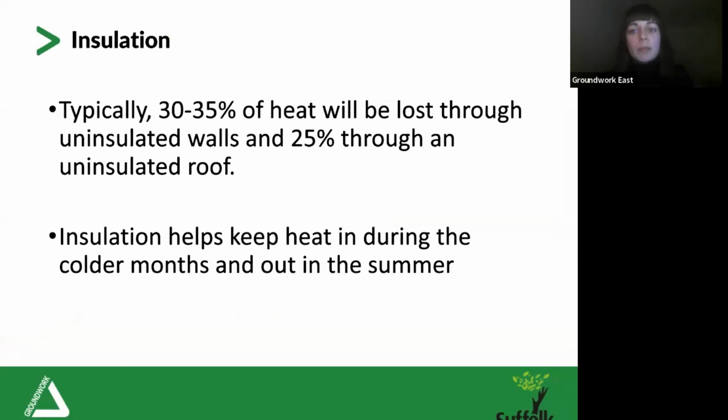Okay, so insulation. Heat loss through floors, ceilings and walls in homes can all be quite significant if insulation levels aren't at the recommended minimum. Let's look at what we mean by heat loss and how we imagine the flow. In winter, heat flows from a heated living space to the outdoors, and it can go into adjacent unheated attics, garages or basements. It travels through interior ceilings, walls and floors. Basically, wherever there is a difference in temperature, it will travel.